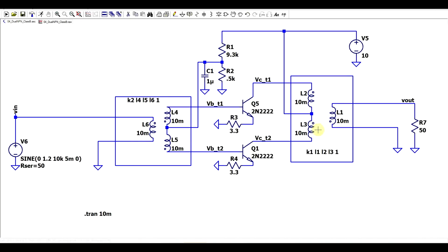So using this sort of transformer, now I have all three inductors of the same value, but you can use any turns ratio you want. So you can go from high impedances to low impedances, or any way you see fit. These sort of arrangements were quite common in older transistor audio amplifiers, or at least the output stage is built in a similar fashion in vacuum tube amplifiers.